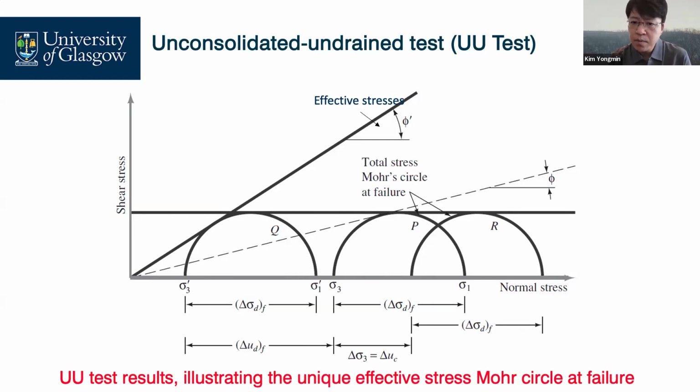When we adopt an effective stress analysis on unconsolidated undrained triaxial tests, as the test is undrained, the excess deviator stress is taken up by water, which increases the pore pressure, right?